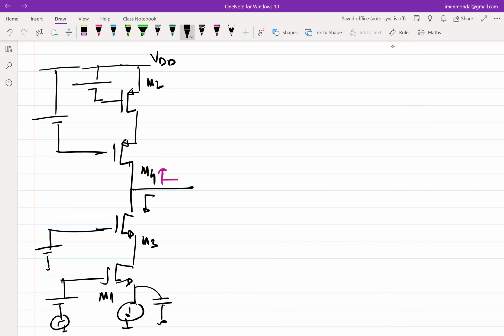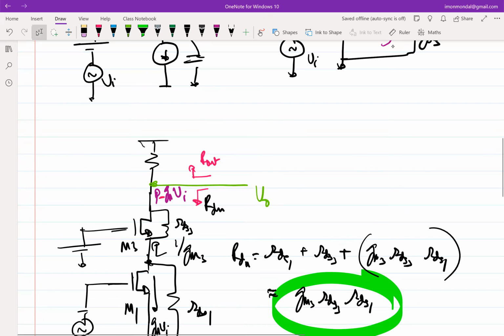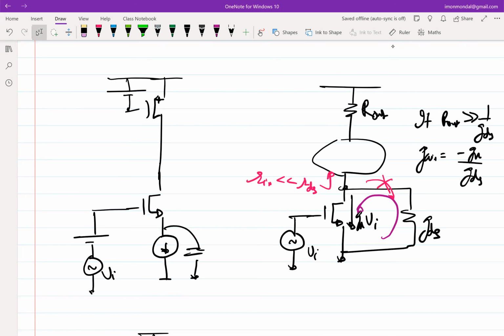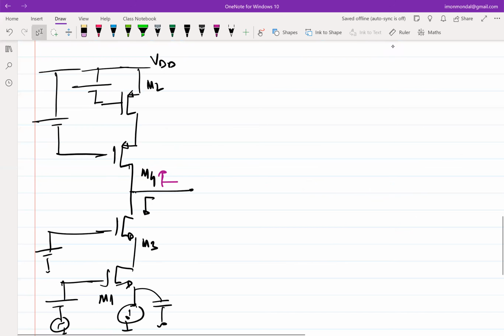Right. So the output voltage swing will be a problem because earlier, in the left structure here, the output voltage V0 could have gotten higher, almost close to VDD, right? One V overdrive near VDD. V0 could have gotten that much. And V0 in this case can go down one threshold voltage below the gate voltage, right? So it almost has a full rail to rail swing that is available.